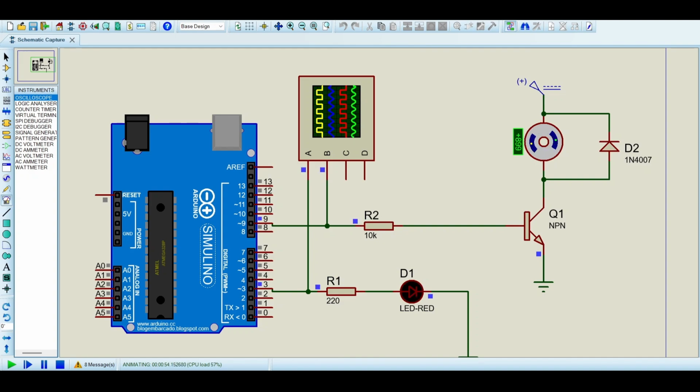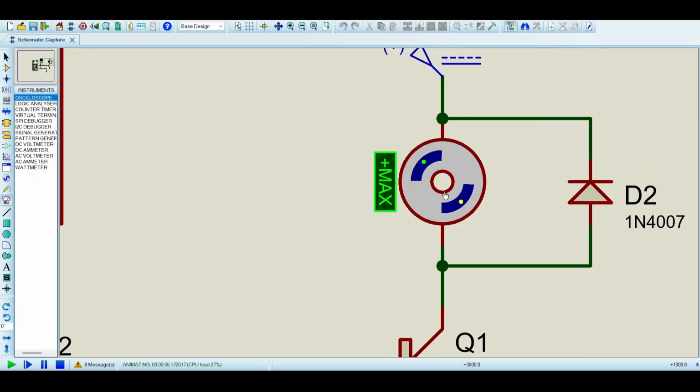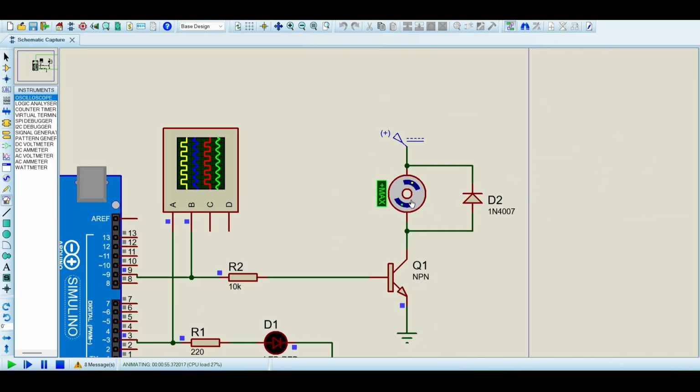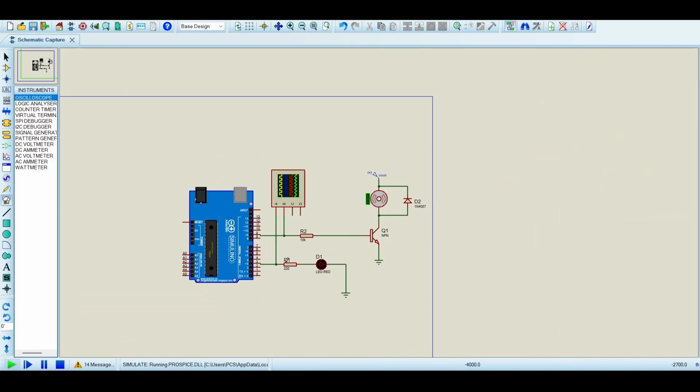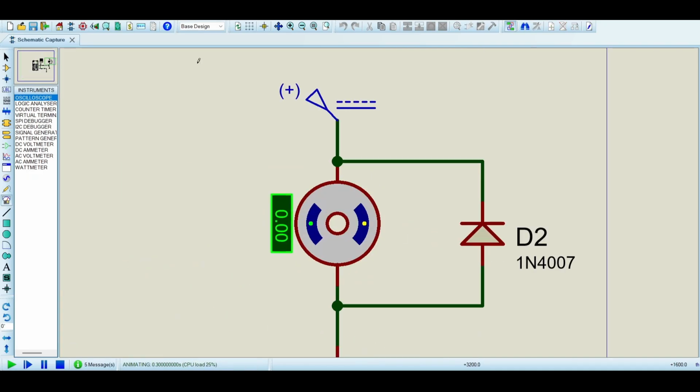Summary: We used analogWrite to control brightness and speed. We used PWM pins 3 and 9. We made values go up in steps of 55, with half-second delays. We added a 3-second pause at the end of the loop. We can visualize the PWM waveform using an oscilloscope.